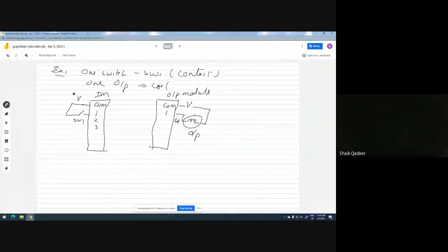Suppose we have a bulb, a DC bulb, which works with 24 volt, right? So 24 volt supply we are directly applying, and apart from this we need to give ground also. That ground we are controlling with the help of PLC program. We always do like this. High supply is already connected. Low supply is controlled with the help of PLC program. Agree or not?